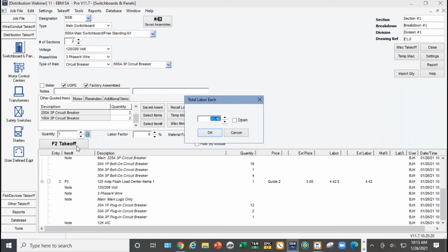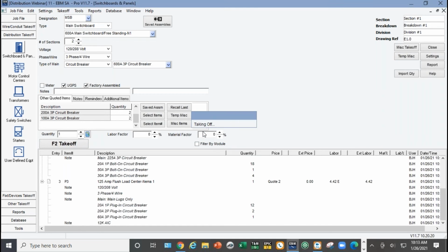You can also change it later, but it's one of those areas where people seem to disagree quite a bit. I find that switchgear really is something you want to have more cushion on than other parts of the job, because there's more handling involved as far as getting approval and submittals on the switchgear. It's a custom order item. You've got to coordinate shipping, all kinds of things that don't necessarily come into play with other parts of the job. So in my mind, you want to have plenty of time here on the switchgear.